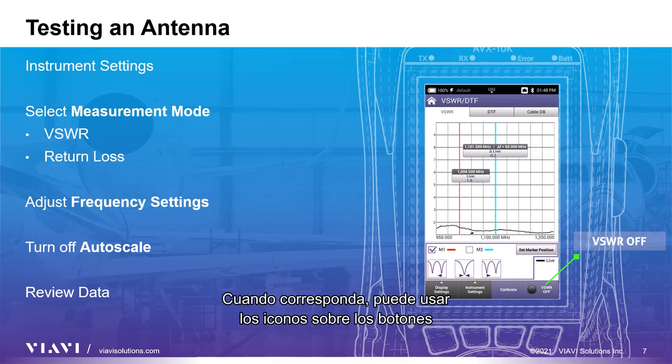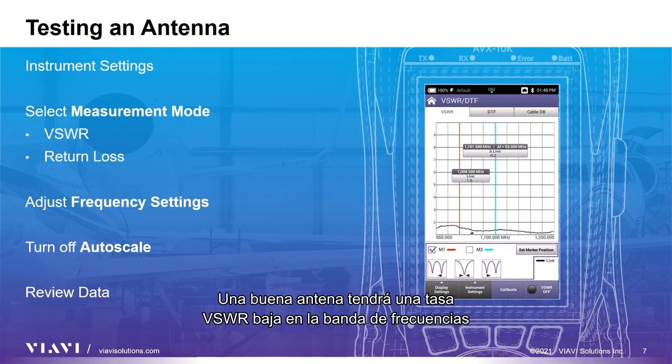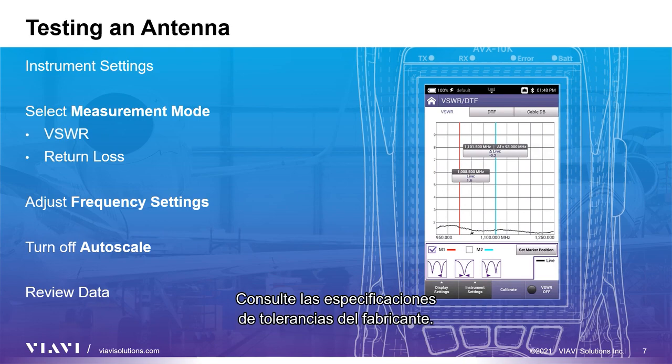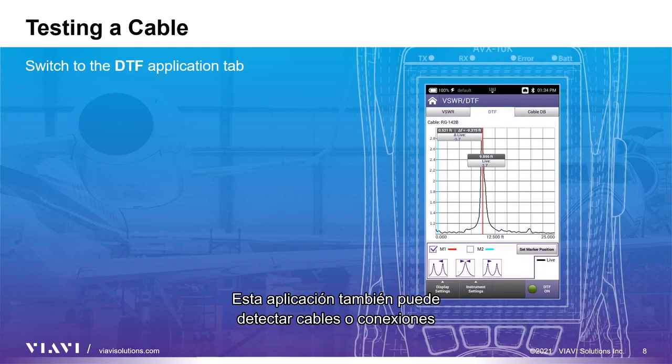When applicable, you can use the icons just above the soft key labels to quickly find the main valley of the signal and then jump left or right to see other valleys in the signal. A good antenna will have a low VSWR ratio in the intended frequency band. Please see the manufacturer's specifications for tolerances. This application can also help determine faulty cables or connections.